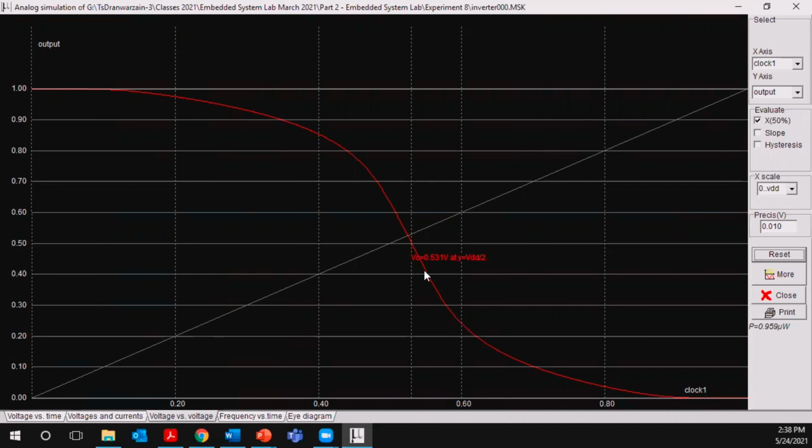So here your obtained graph is around 0.5314. So that means you put the input of your voltage around 1 volt, right? This is 1 volt. So it should be half, VDD over 2. VDD over 2 means that you are at optimal value, which means your result is correct or optimal. Okay, you should obtain this graph.